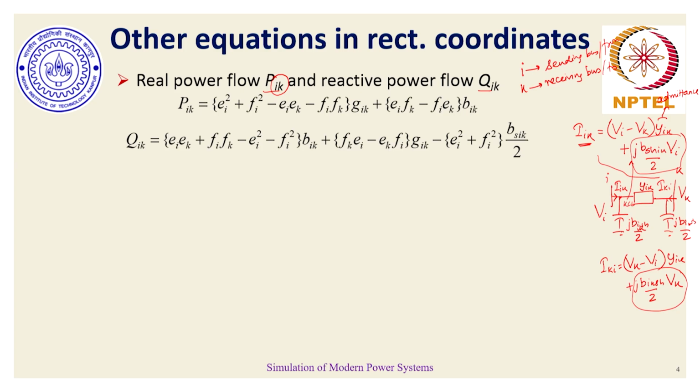I did not explain how you would find the current across two buses which are connected through a transformer tap, based on which the corresponding Pik and Qik expressions are going to be different if we have transformer taps present between bus I and bus K. I request you all to please take a look at the discussion where we discussed the consideration of transformer taps between bus I and K, depending on the position of the tap. So let me probably draw the diagram.